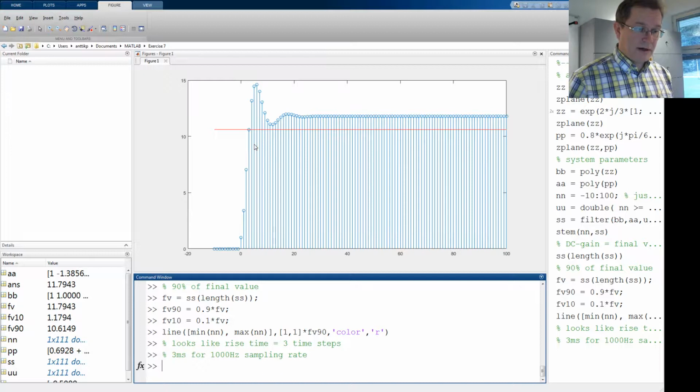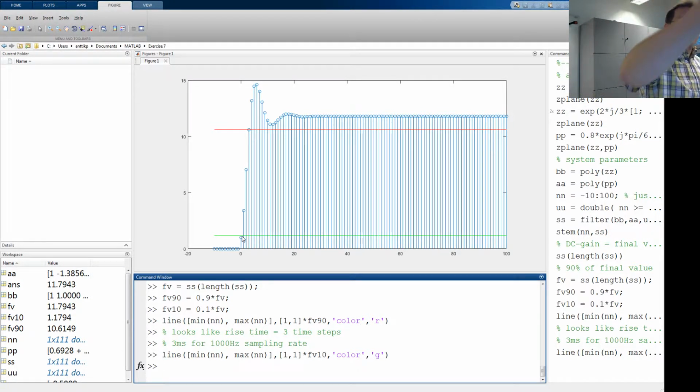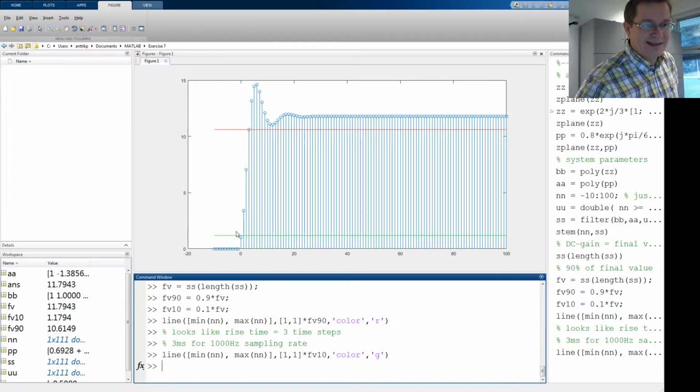And then the other line is 10, green. Okay. So rise time is more or less, it's not 0, it's actually 1. Rise time cannot be 0. So linear estimation actually would give you some 0 point something, but remember, time is quantized here. It's a sampled signal, sampled system. The delay time is not 0 because this is less than 10%.